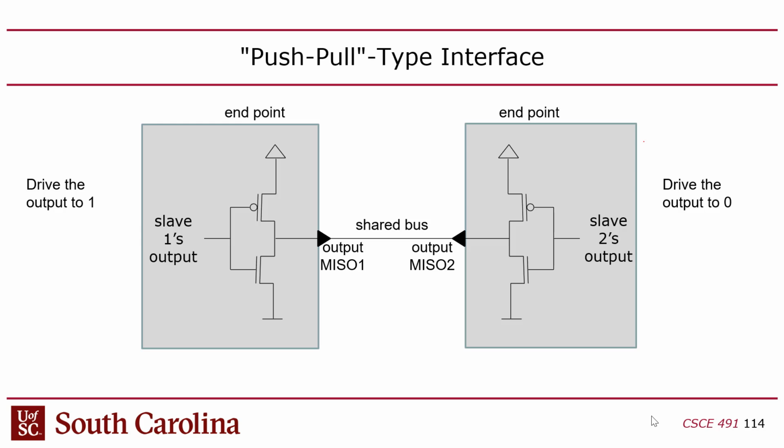And an inverter has two transistors which function as a way to take the output and pull it to VDD, meaning that one of the transistors closes and the other one opens, right? Or vice versa. So you only have one transistor open at a time.